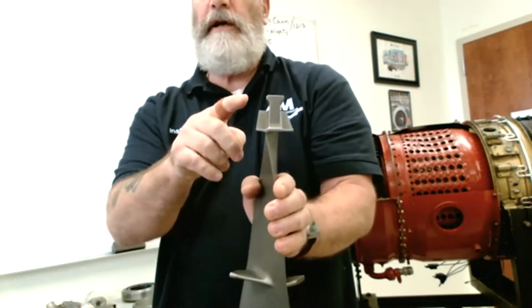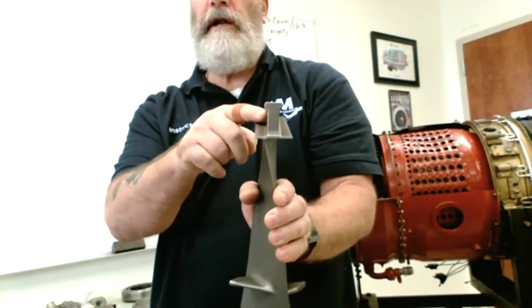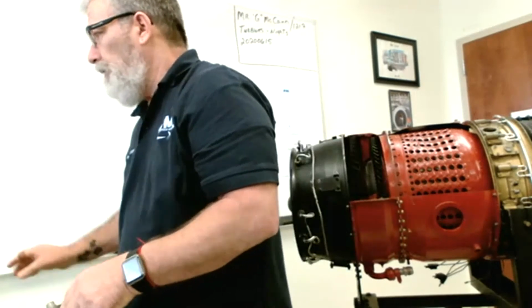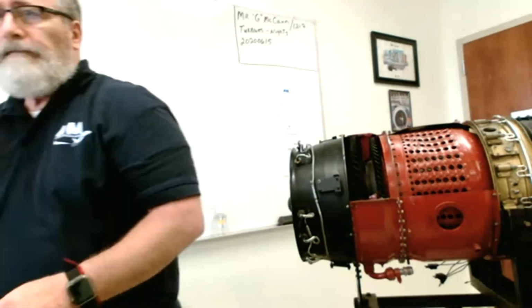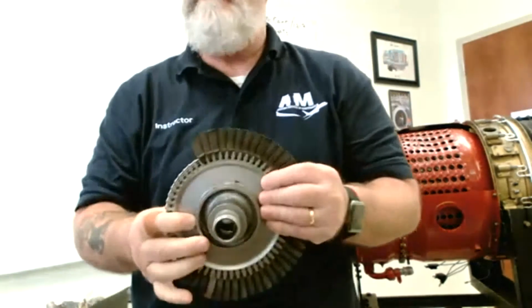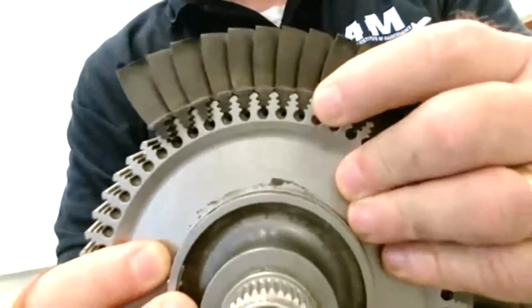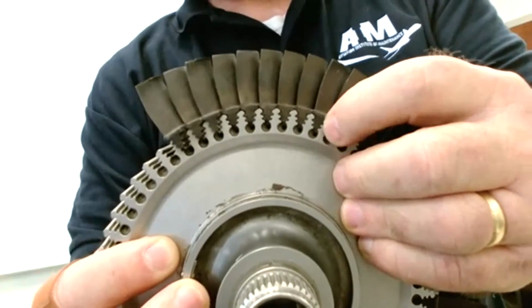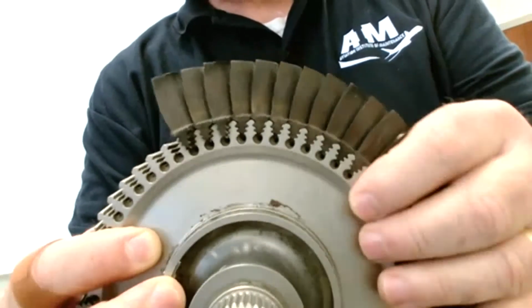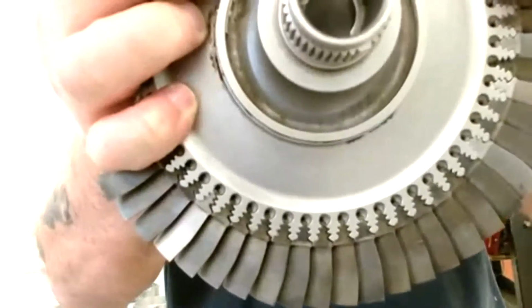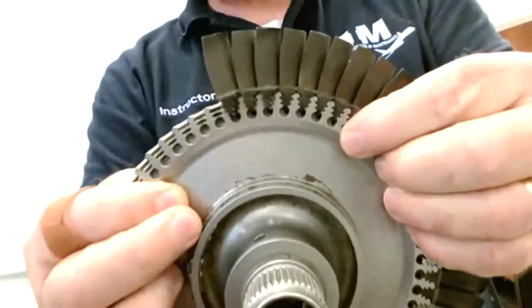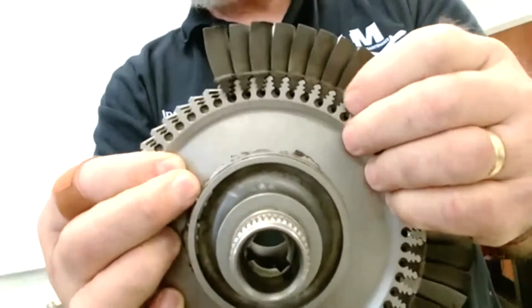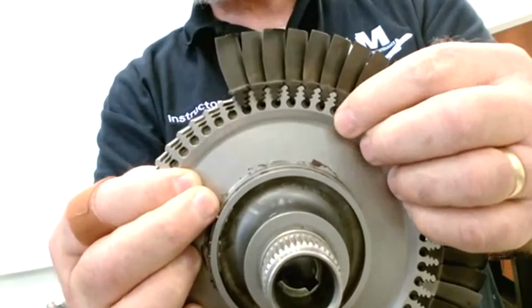This is known as a dovetail attachment. As you can see, it kind of resembles a dovetail, all right? Now, on turbine blades, by far the most common, and this is the FAA's favorite, you can see where these blades are inserted into this disc. If you think about it, these kind of resemble a little Christmas tree upside down. So these are referred to as fir tree attachment, fir, F-I-R, all right? Not fig tree or plum tree, not Christmas tree, right? These are fir tree attachments.